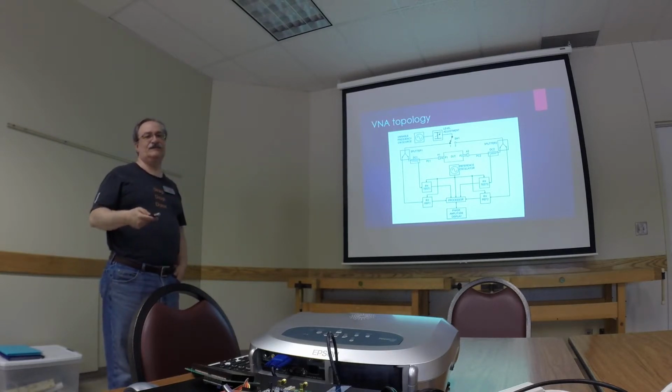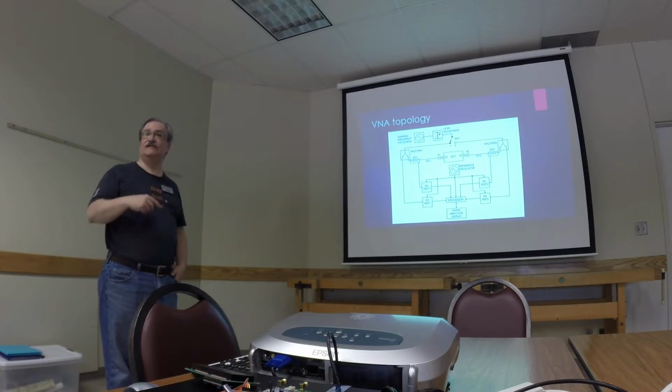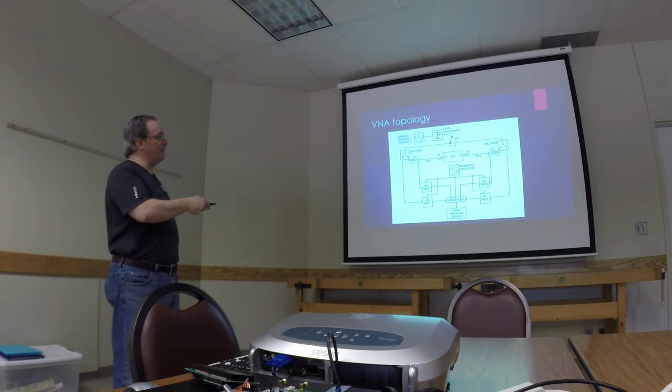The other thing they do, and this is the case with this kit, is that the DDS actually has 2 ports and 2 programming modes, so it can run simultaneous frequencies. So you can take a point of interest for the reference oscillator feeding into the receivers, or what they're calling receivers in this diagram, and then make a comparison from the leveled sine wave here to the device under test in terms of what's been reflected back.